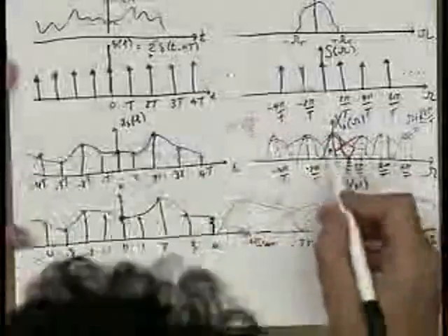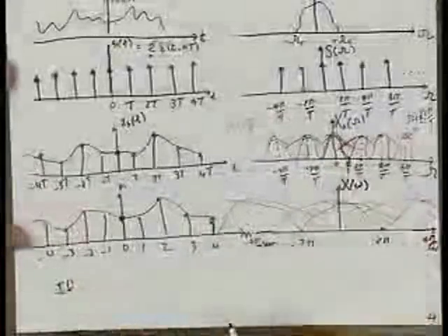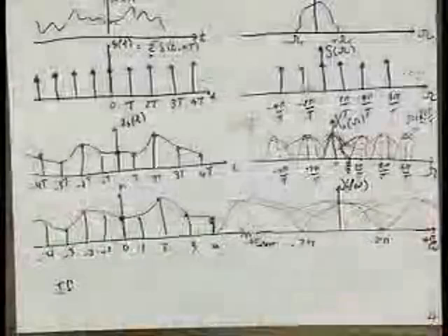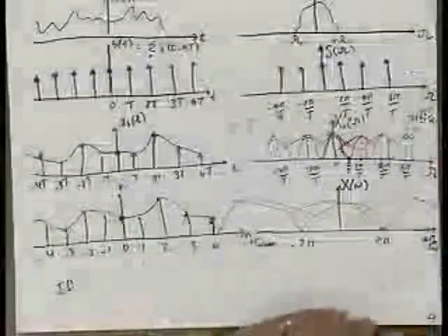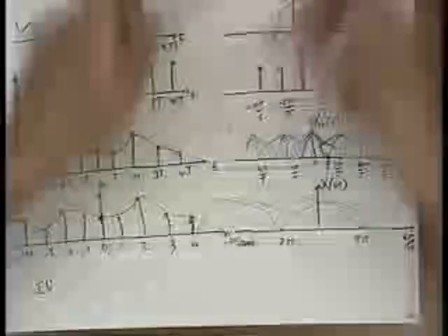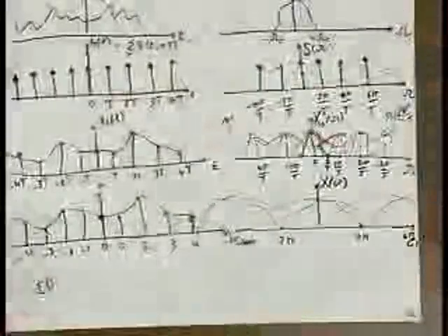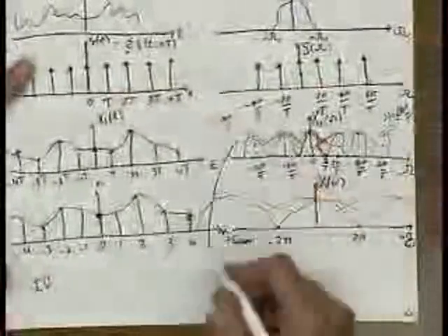And so in the green case, what's this frequency? That's also omega c, right? So if I want no aliasing to happen, omega c has to be smaller than what? Pi over T, not 2 pi over T. So I caught my own mistake. So this is pi over T, and this is pi over T. So let me, is that obvious? Let me blow this guy up down here.